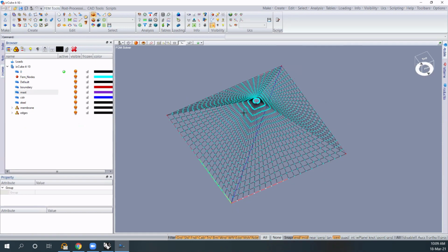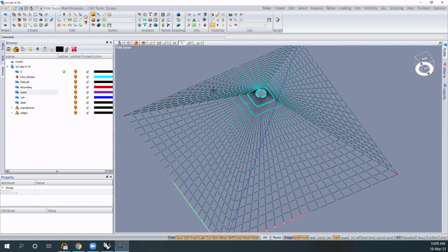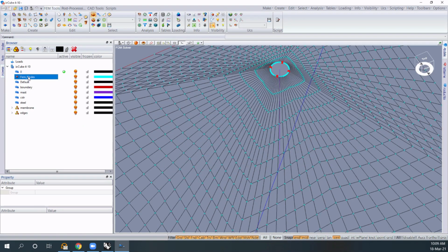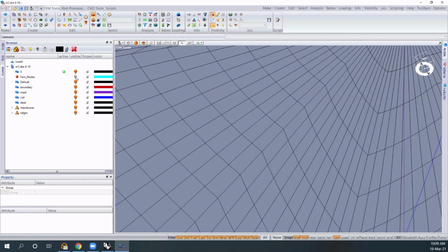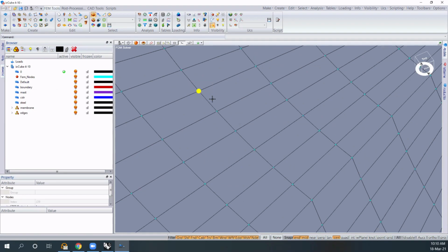What we're using for running the form finder is, let me tell you, one special group: the FEM nodes. The FEM nodes are these dots here. So you can unhide the nodes from this layer here, or from this tool, it's easier here. The nodes are FEM nodes. Now, for engineers out there, I don't need to say anything about what a FEM node is.